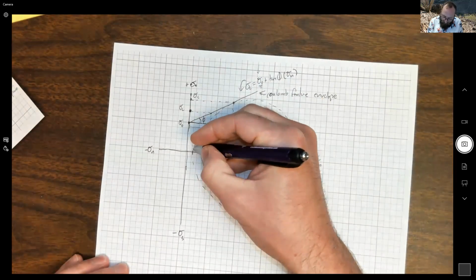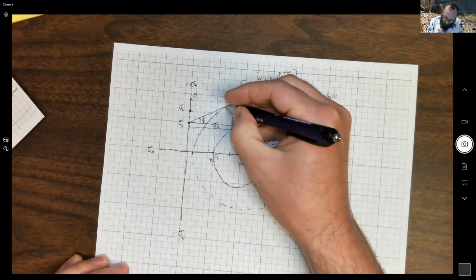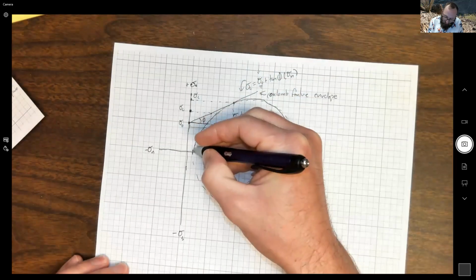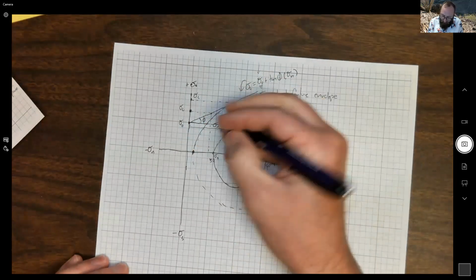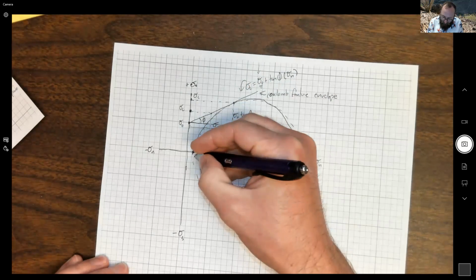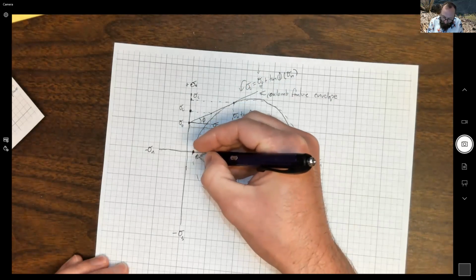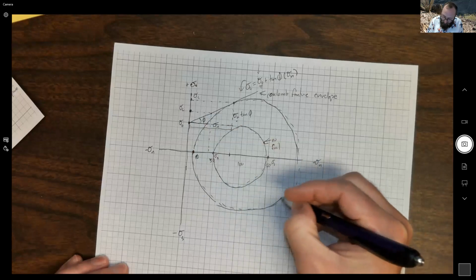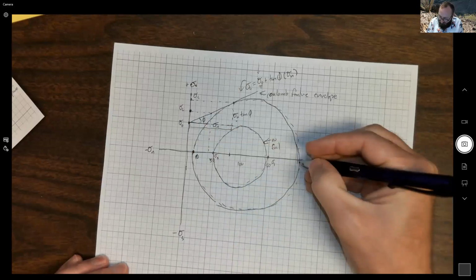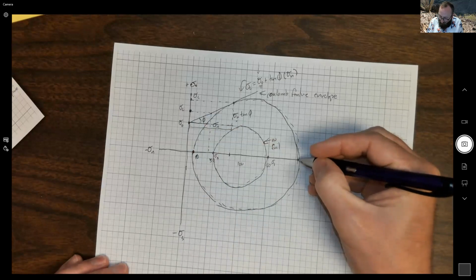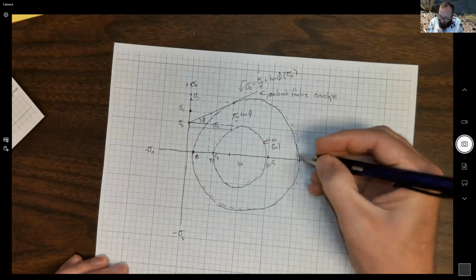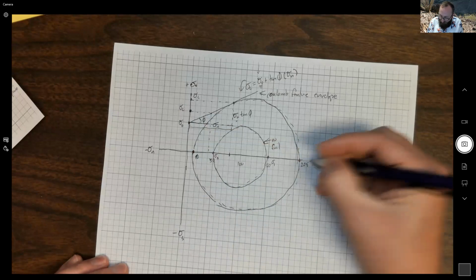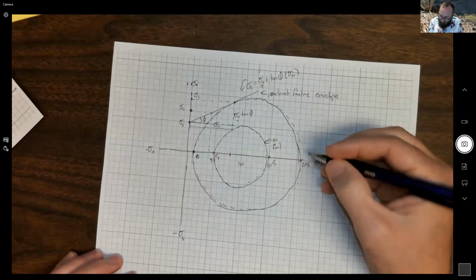Whereas this circle is big enough that we started with a confining pressure of, say, 10 MPa, and we kept ramping up our maximum principal stress until we got to actually about 205 MPa, just based on how I've drawn this circle.